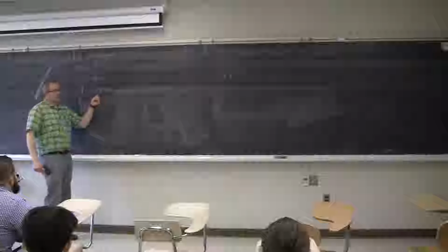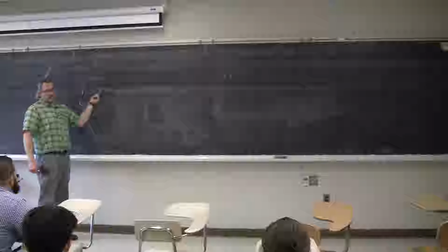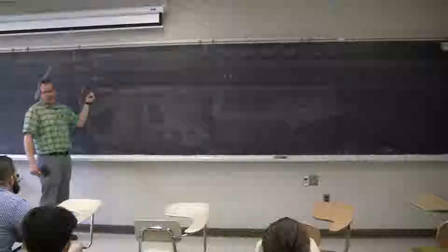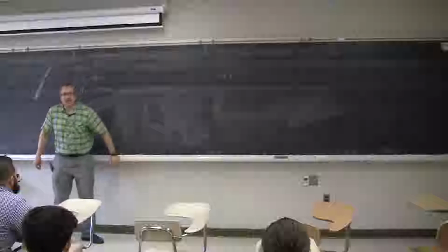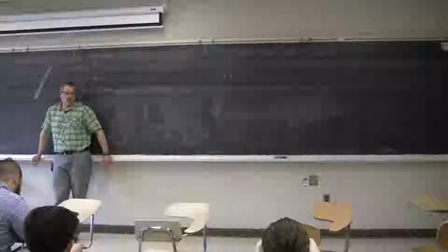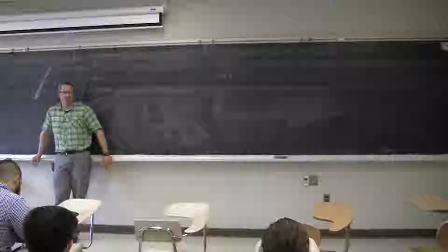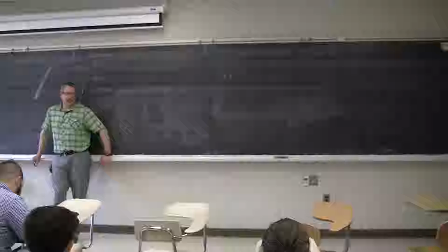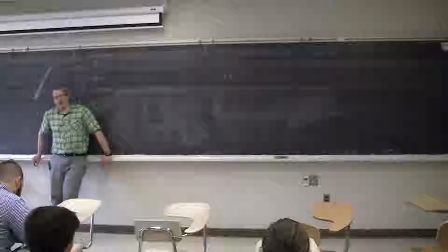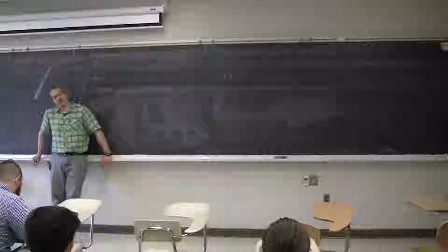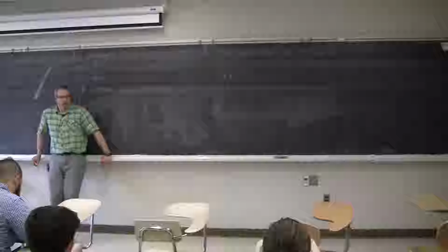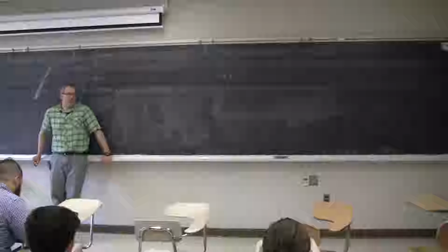So a synchronous machine has a stationary field that is going to be connected to the AC supply, and a rotating field that usually is going to be connected to a DC field that you can vary. And the reason why you vary it is because you either overexcite the machine or you under-excite the machine. It depends on the connected load. If you want a leading or a lagging power factor, you either need to put more reactive power into the machine, which means more DC field in. If you want to be able to take magnetic energy from the circuit or from the system you're connected to, you can put less magnetic energy in, meaning less DC field.